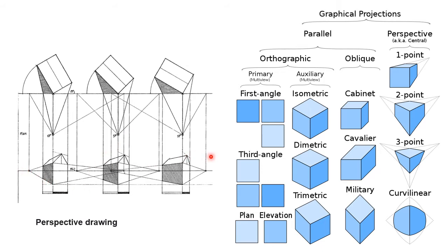The most distinguishing characteristic of perspective is objects appearing smaller as their distance from the observer increases, and they are subject to foreshortening, which means that the dimensions of an object along the line of sight appear shorter than the dimensions across the line of sight.